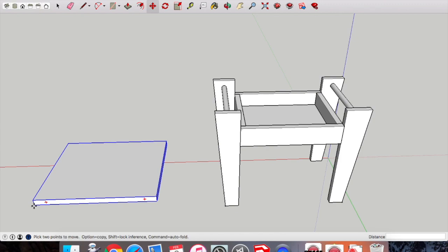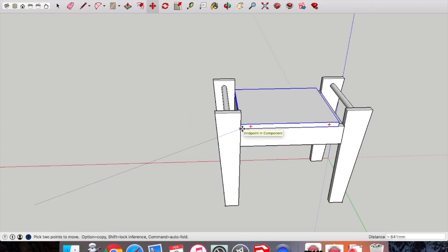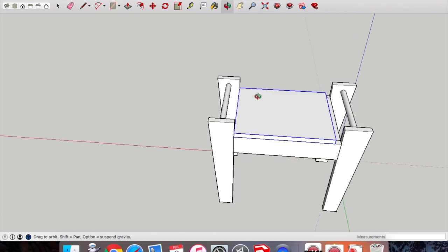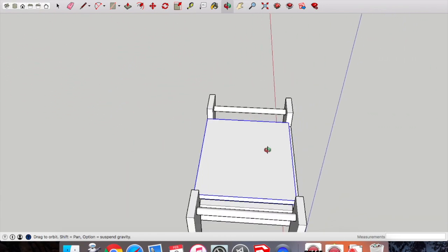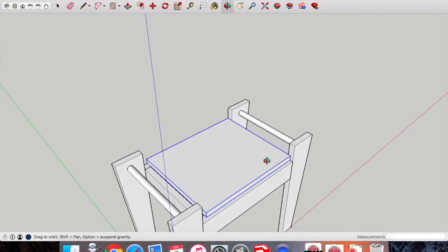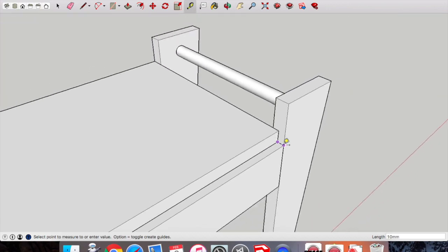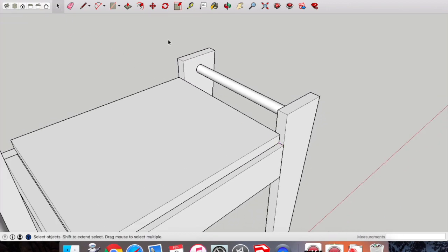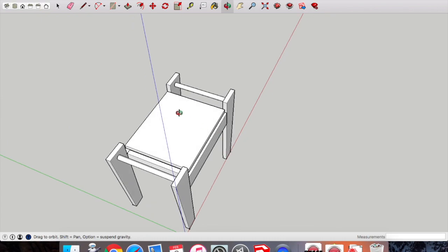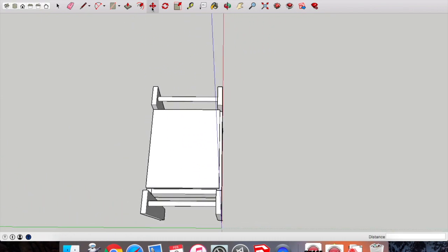So I'm going to move, so bring out that bottom point there of the top, and just marry it up with the leg. At the moment, you can see that that top's smaller than what's required. That's because we have an upholstered stool, so we need to leave enough room for the fabric on all the edges. See that that's 10 mil off here, so what we're going to have to do is drag that top 5 millimeters to the right, so we have a 5 mil gap on both sides. But start dragging that in that direction and type in 5 and press enter.